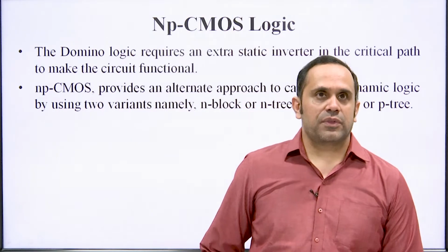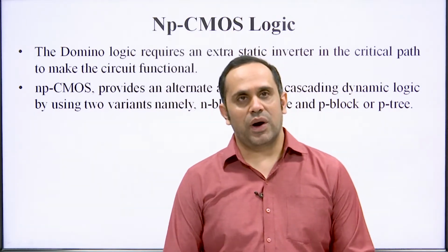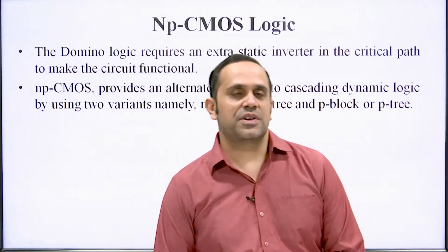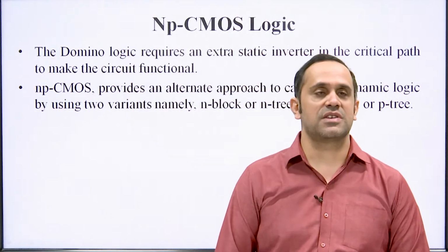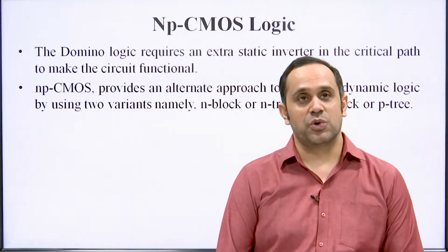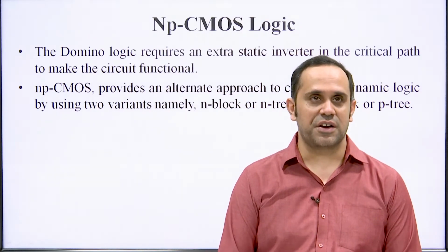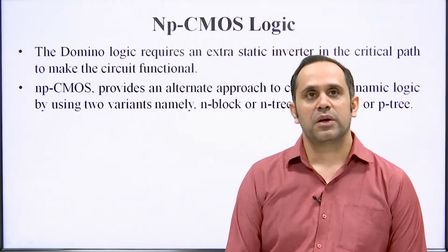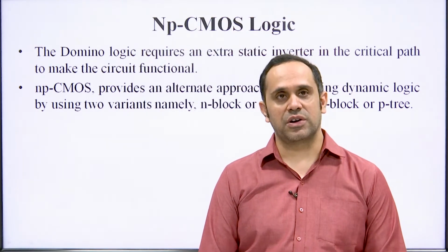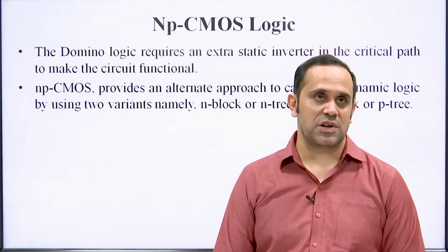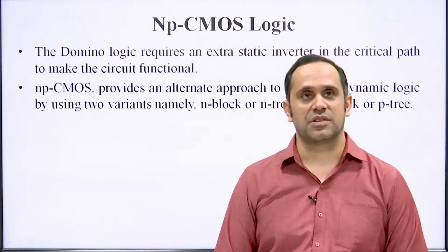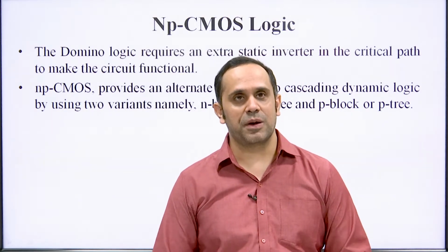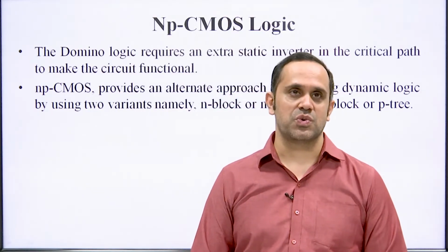So, till now we have seen quite a few design methodologies. We have seen static CMOS design, where there is no role of a clock, the signal remains as long as they are there, the output keeps on calculating. It offers very good noise immunity, it is very robust, but then it uses a lot of transistors. So, scalability and increasing complexity are an issue.